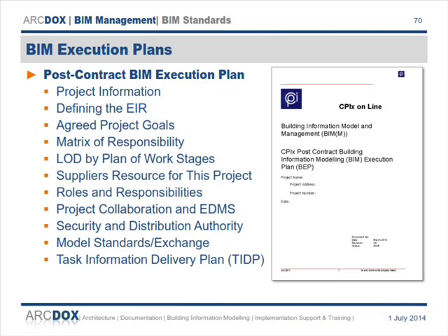But I would say, from experience, you give a bunch of documents to a contractor and say build that, but you're not really saying build that to those documents. You're saying build that, produce a whole series of fabrication or workshop drawings for the building, and build from those. So for the most part, the contractor is not building to the engineer's drawings, he's building to the precast guys, the steel fabricators, the glazing contractors, the balustrade fabricators' and staircase fabricators' drawings. He doesn't build an awful lot to the architect's drawings, other than basic setting out.